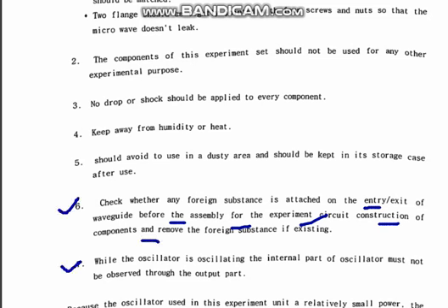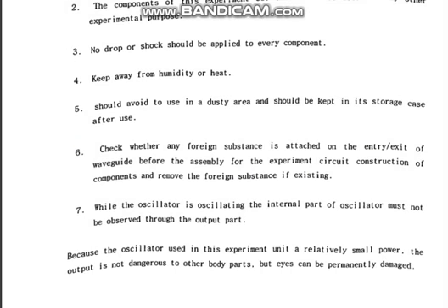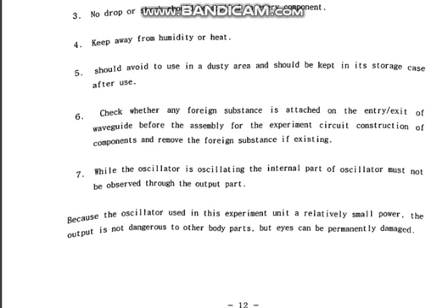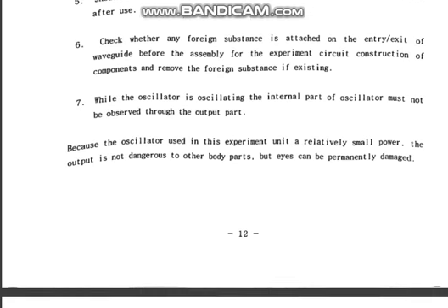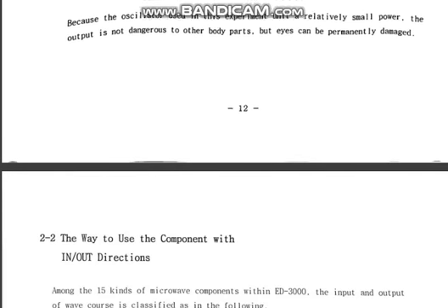While the oscillator is oscillating, the internal part of the oscillator must not be observed through the output part. Because the oscillator in this experiment unit is relatively low power, the output is not dangerous to the body parts, but eyes can be permanently damaged. So we have to keep our eyes safe from the microwaves. That is an important thing.